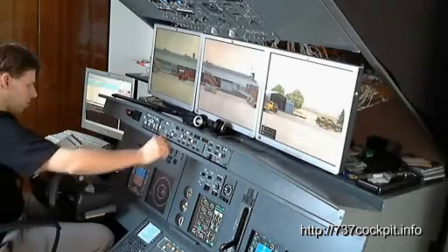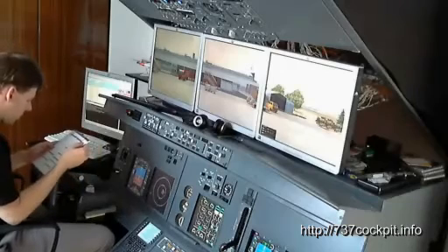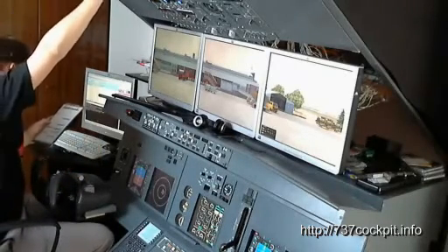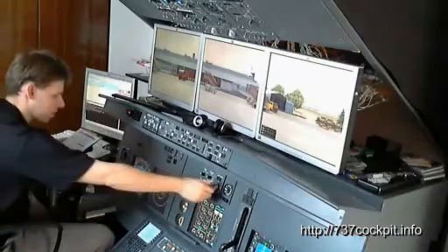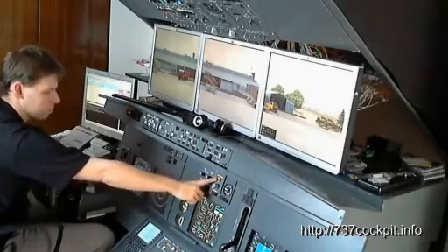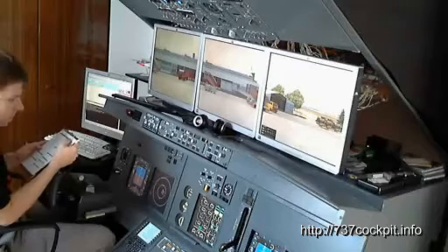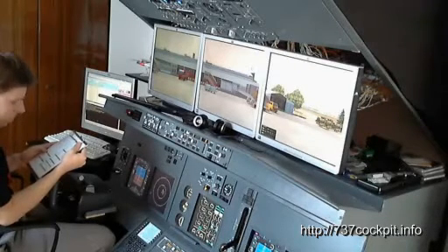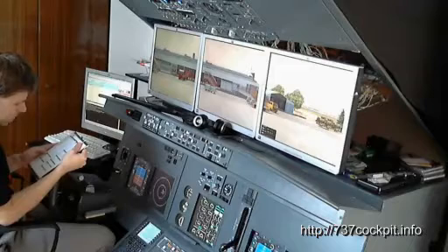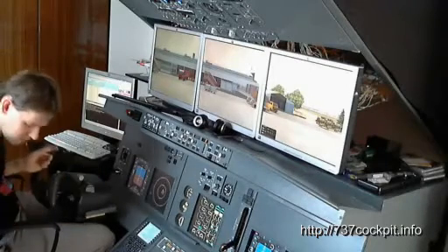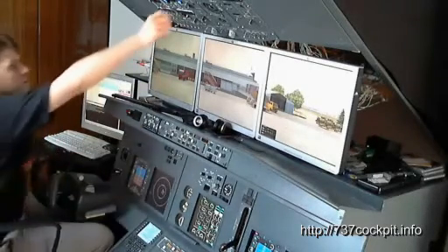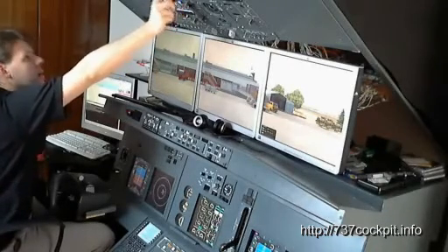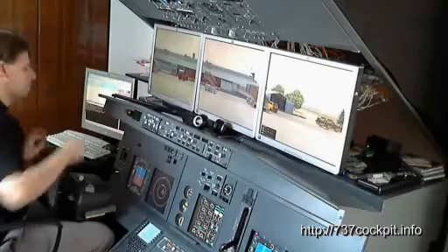Flight director is on. We can see now our flight director. Flight controls on. Instruments cross-checked. Auto brake reject takeoff. It will perform an auto test and will go off after 3 seconds. That was correct. Takeoff briefing. Boarding is not completed right now, and no smoking seatbelt sign. No smoking is of course on the whole time, and boarding is not completed until now.